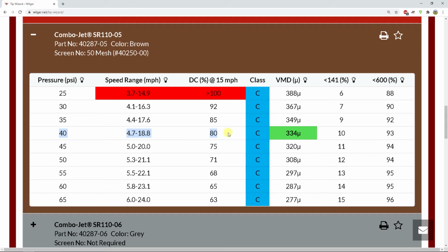So with turn compensation, what it does is use that extra capacity. In this case, we'd have 80% of our spray in the center section, meaning there's 20% more, or extra, capacity on that outside section that's swinging hard. So turn compensation is able to take advantage of that extra capacity, open those solenoids out for a longer duty cycle, and put more chemical out such that you'd have a more accurate rate going down in those corners. So 80%, great, no issues there.